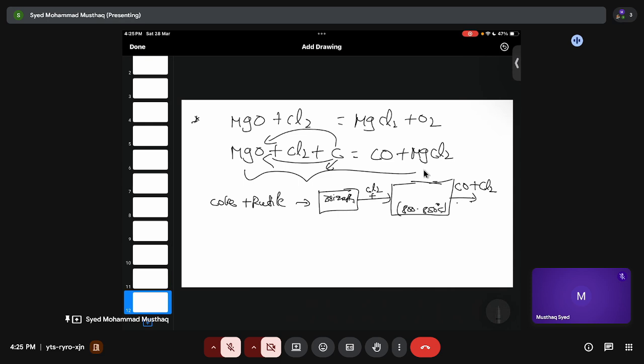And because again we have said highly volatile, so you will end up with gases, right? So after dedusting, you will have titanium chloride. And what are the other things that you get? You will end up with the leftover rutile, the coke that is reacted and left, and the dust also. You will have TiCl4, and then you do the condensation.